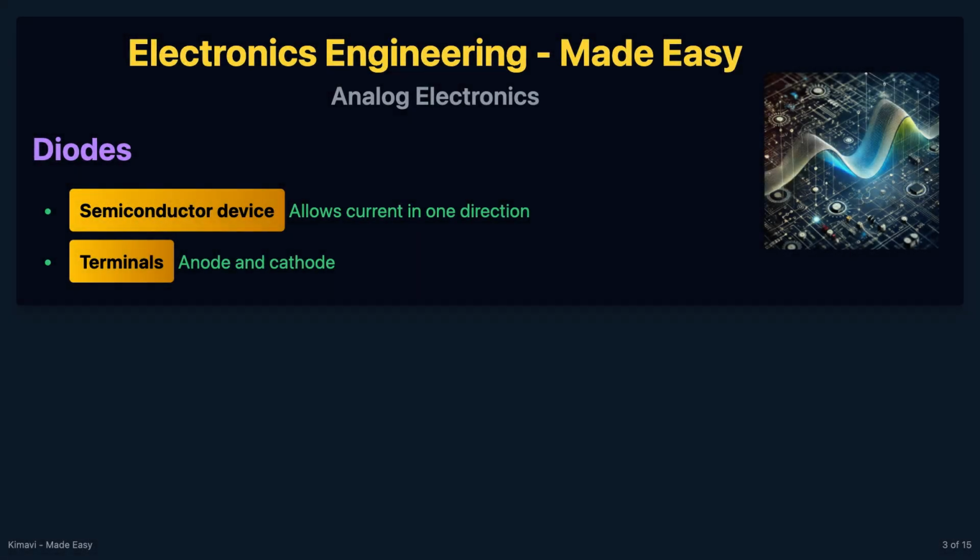A diode is a semiconductor device that allows current to flow in one direction only. It has two terminals, an anode and a cathode. When the anode is at a higher potential than the cathode, the diode is forward biased and allows current to flow. When the cathode is at a higher potential, the diode is reverse biased and blocks current flow.